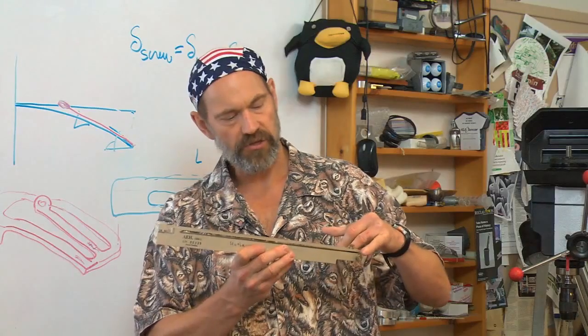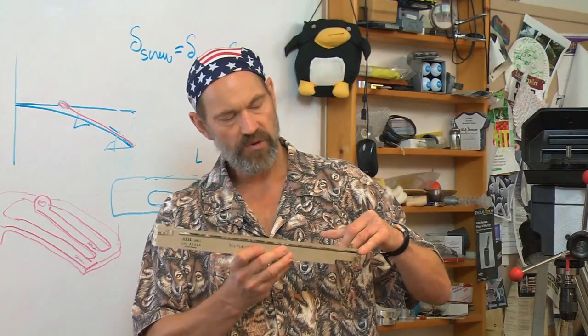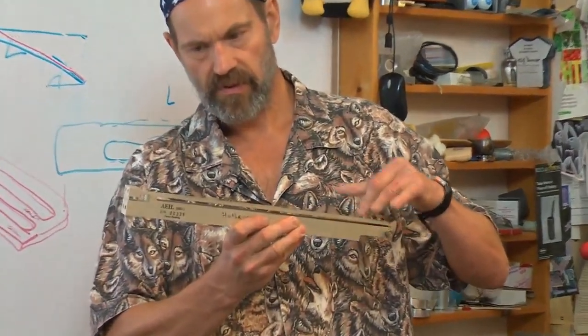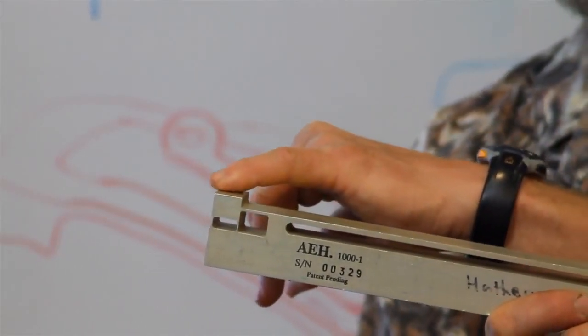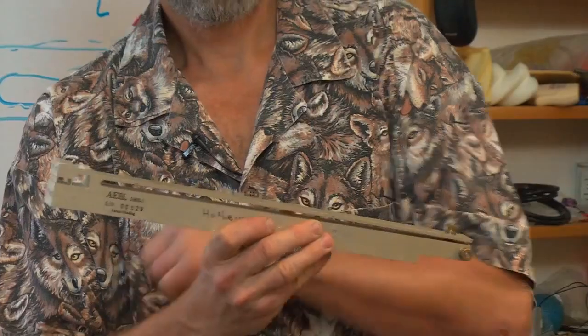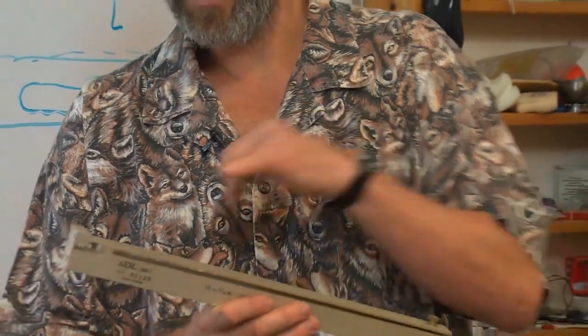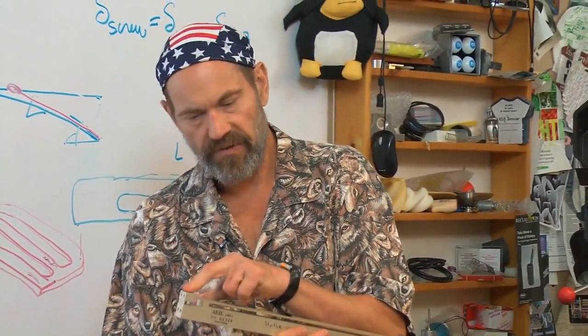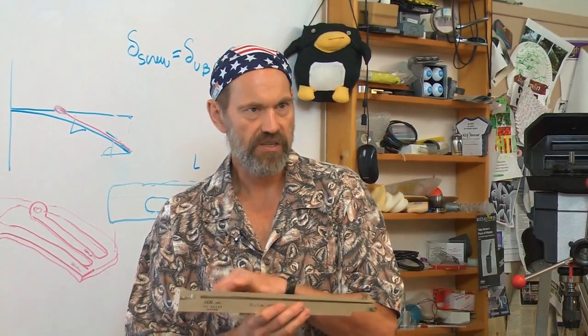It moves 1/1000th of this motion. So in other words, if I move this here 1 millimeter, this stage here has gone 1/1,000,000th of a meter in motion. That's fantastic. Now you can't make this stage move 10 millimeters by this method, but for very, very fine control, for example, in some special types of microscopes or cell manipulation systems, you can use this kind of effect.